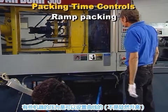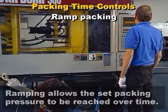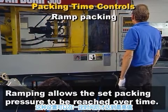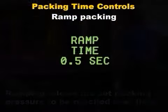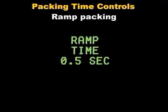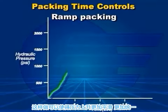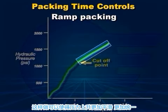The hydraulic controllers on some machines ramp the pressure used for packing. Ramping allows the set packing pressure to be reached over time. For example, if we set a ramp time of a ½ second, it will take ½ a second for the pressure to reach the pack pressure setting. The advantage to using the ramping capabilities of your controller is that it smooths out the pressure curve of cavity packing, resulting in more uniform and consistent part characteristics.